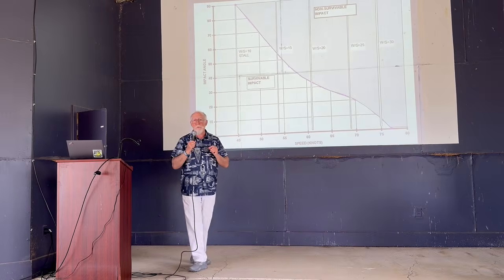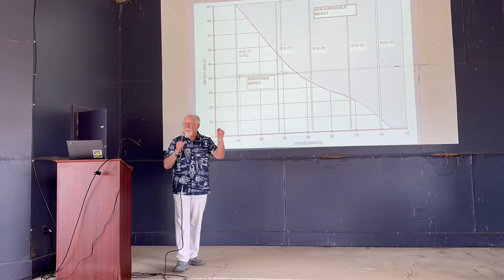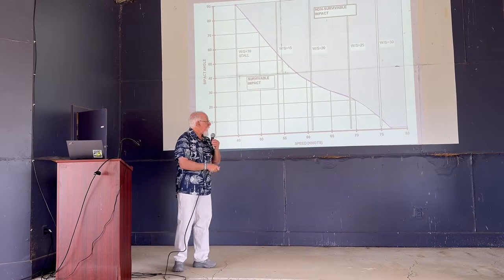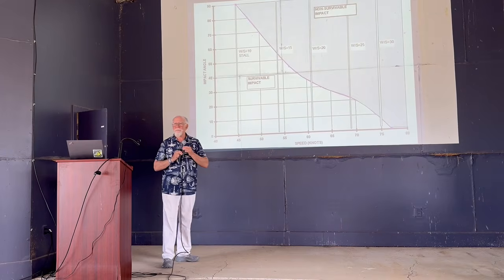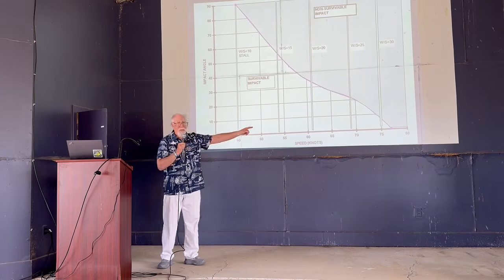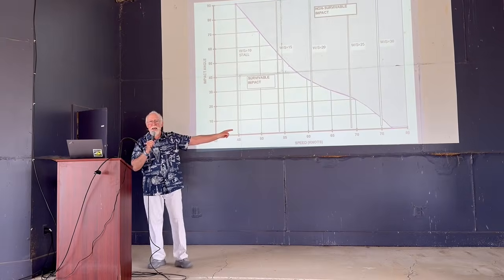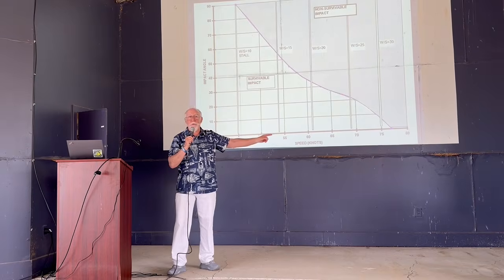Here's the one for people who are playing with high wing loading experimentals, because in EAB we don't have that stall speed requirement. Out here at about 78 knots, even a flat impact on random terrain will probably kill you.